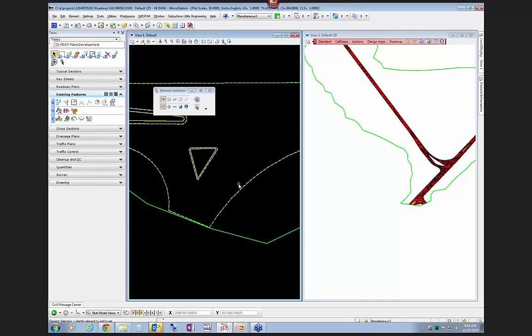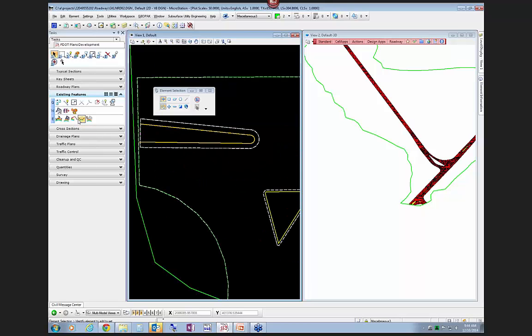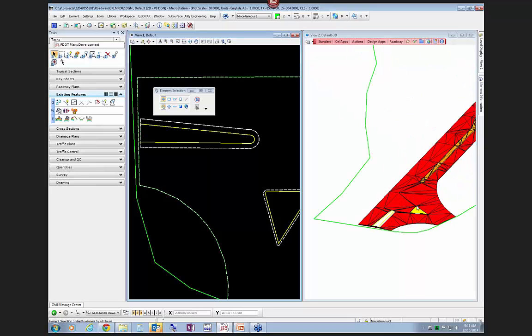Now I can use the linear template tool, which is this one right here, because in order to apply a linear template, it has to be a civil geometry element and it needs to have an active profile. Once you have that, then I can place a template shape around the perimeter of this line, and it will fill in what normally would be the bottom side of the curb, the back and bottom, and sort of front, anything but the top, because the existing terrain will fill in whatever the top is.